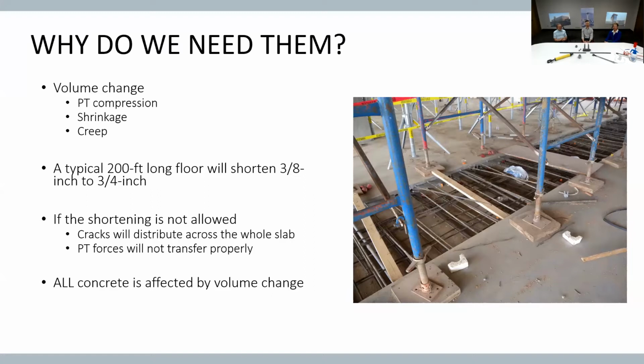And don't use the answer that, well, that's typical, because it isn't. And the other one that I don't know that a lot of engineers pay a lot of attention to, but if you've got two anchors or shear walls at the end of your slab on a 300-400 foot long slab, those forces of the PT often are transferred directly into those shear walls.